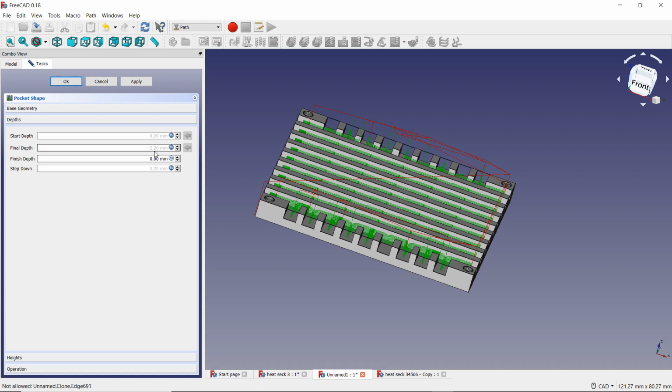I put the negative 2.2mm to put that negative number, and then it doesn't move up, it just moves across to the start point. And then as it's moving across to the start point, it starts to actually go down and cut into the material, which leaves me with my part that I'm trying to create here. So I'm going to put that video in. Hopefully that video helps explain what it is I'm talking about, but if it doesn't, you'll find out as you're using this piece of software.